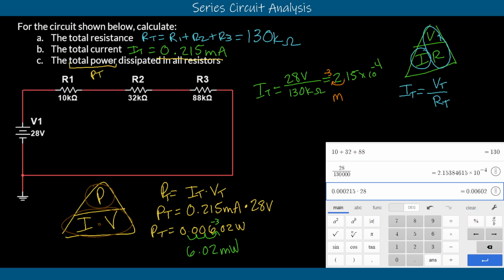That's great. And in fact, it's so nice that we can even leave off these zeros and know that whatever we multiply this milliamps by, this voltage over here, it's going to end up giving us a milliwatt output over here. And so we end up with 6.02. So there is some level of shorthand that you can use with these notation values. Just be careful. And if you are uncertain if you've got it correctly, pull it all the way back down to 0 and account for every one of the zeros that you know you have. Okay, let me know if you guys have any questions.